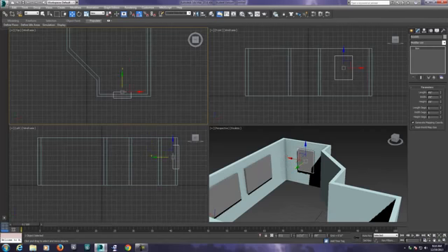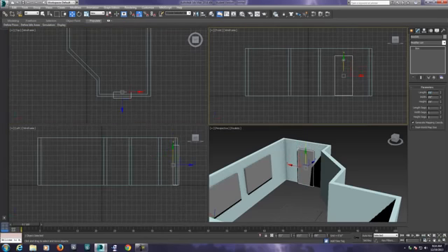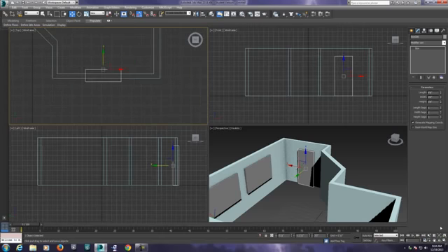And a door is typically, I'm going to say probably 76 inches high, maybe a little bit more. Let's do this. Let's go 80 inches high. Oops, 80 inches high, which is what your standard door is at Lowe's. And your ceiling should be about 96 inches. So there we go. The door is 36 wide, 3 foot wide. That's typical for an interior door, unless it's a small closet or a bathroom.